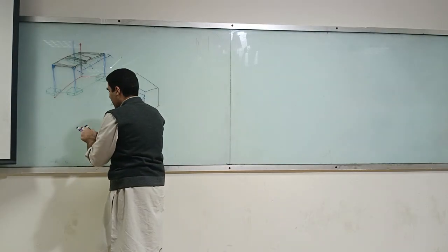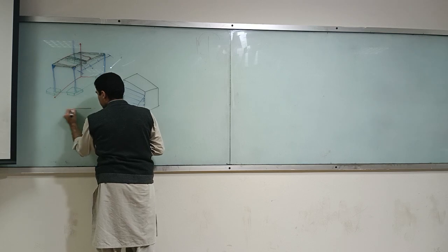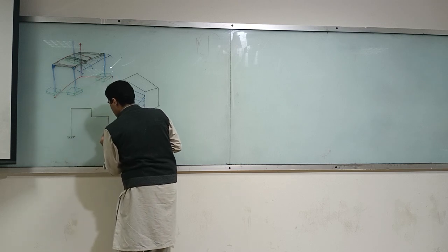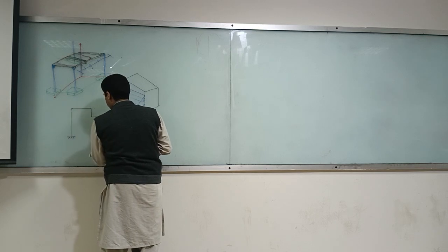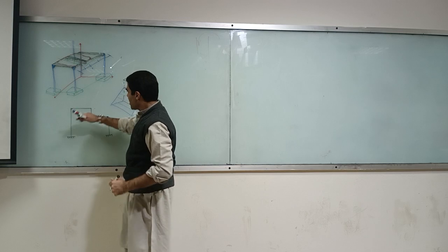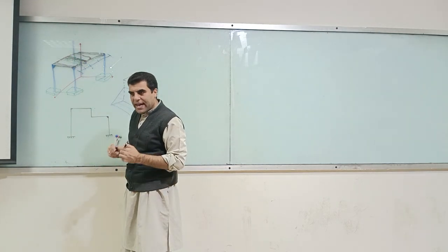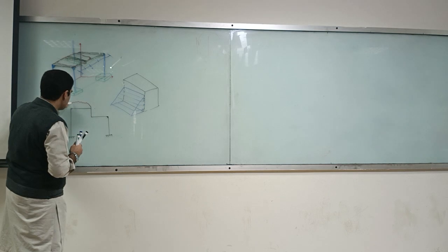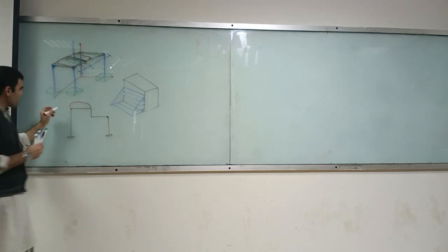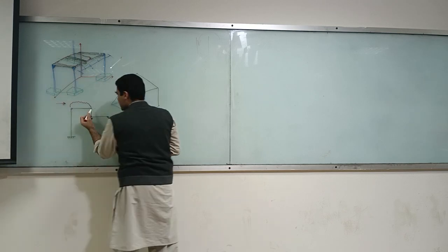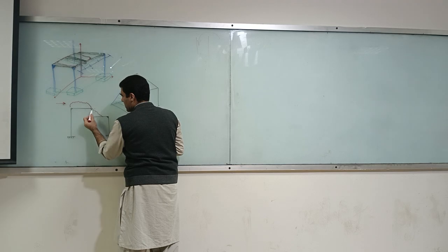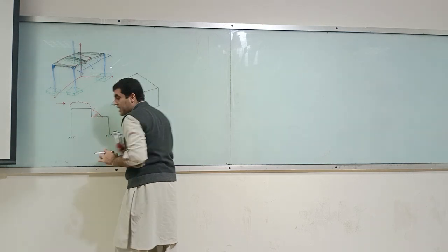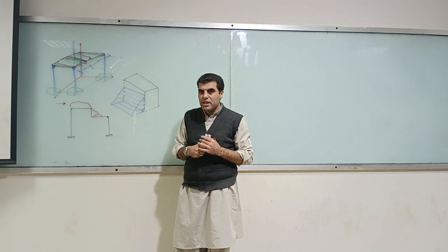The other scenario is if I have a frame which looks like this, and this is a frame which is fixed ended. I'm just looking at a cross section. So I've got the same building, but it is having a frame like this. And imagine there is a snow load placed over here. Due to the wind, your snow gets accumulated over here, isn't it? You will have a snow accumulation. So this is also a linearly varying load. For this one you apply a linearly varying load. So that's also another common place where you can have a linearly varying load.